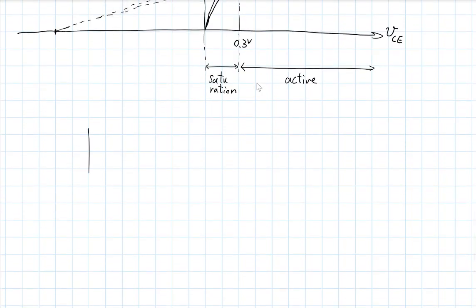Consider a current source, controlled or uncontrolled. This current here does not depend on the voltage across that source, right? What if I wanted to represent an element whose current is mostly this, but still does vary a little bit by increasing that voltage? So the current is not just that, but that plus a part that does increase with the voltage applied between these two points.